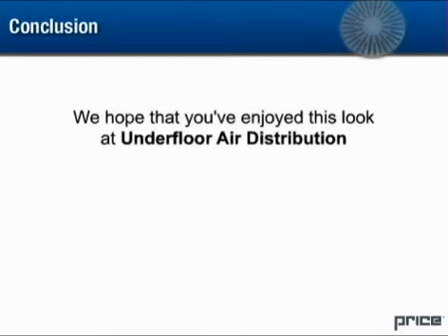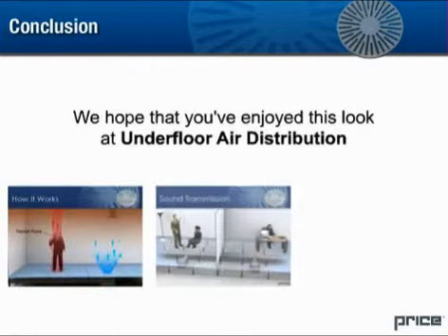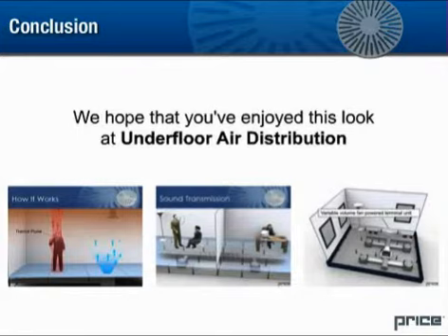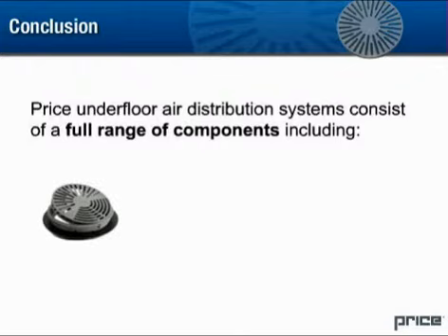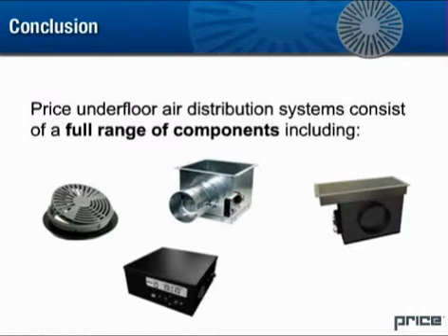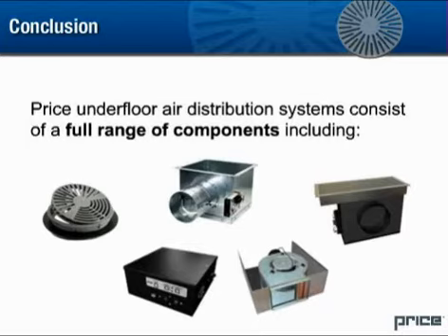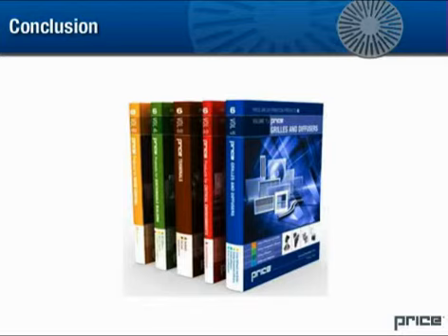We hope that you've enjoyed this look at underfloor air distribution. We've explored many aspects of underfloor air distribution, from concepts to benefits to design considerations. We've also seen that the Price underfloor air distribution system consists of a full range of components, including round floor diffusers, round floor boots, linear floor grills, modulating controllers, and fan terminal units, which may be combined to suit a variety of underfloor applications. For more in-depth information on this topic, you can always refer to the Price catalog.